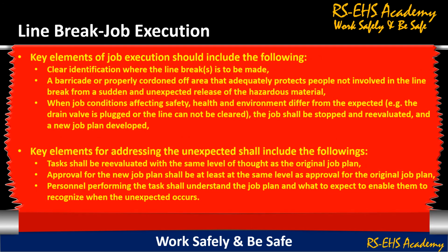Line break step, job execution. Key elements of job execution should include the following: clear identification of where the line break is to be made, and a barricade or properly cordoned off area that adequately protects people not involved in the line break from a sudden and unexpected release of the hazardous material.